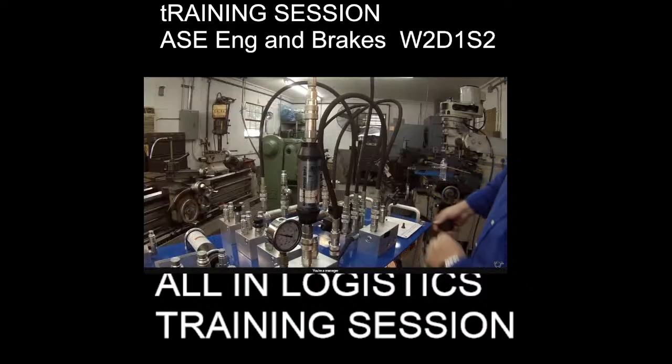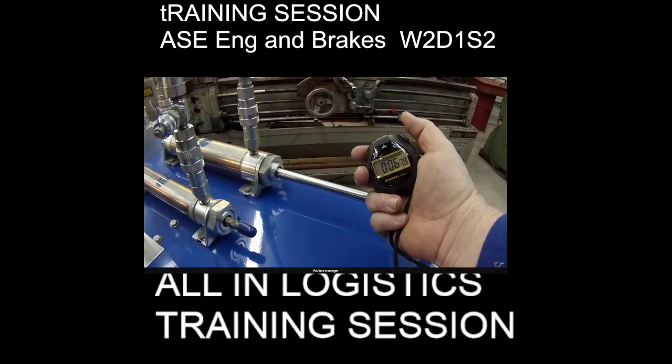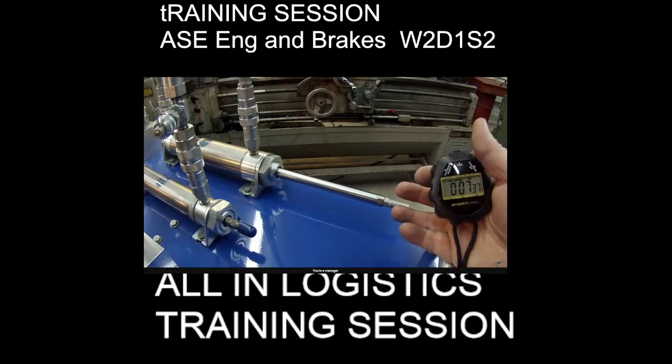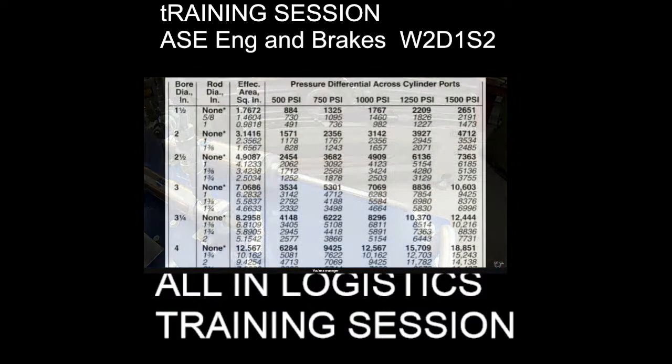So a little less than 1 gallon a minute, something like that. And then we're going to time this coming back out, and it should be about half. It may vary just a little bit because the oil is kind of cold. Alright, that was perfect. It's about 7 seconds. The other one's about 4 seconds, so that's perfect. So the point was that when your flow drops, the speed slows down. When you're troubleshooting a hydraulic system, it's very important to understand that flow is speed, and if you're not moving as fast as you're supposed to, you're losing flow.